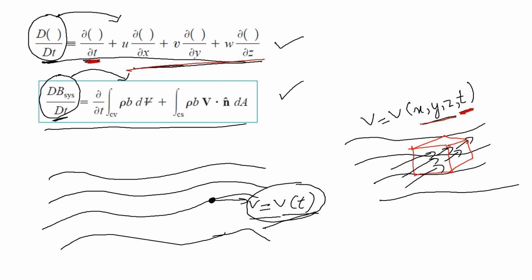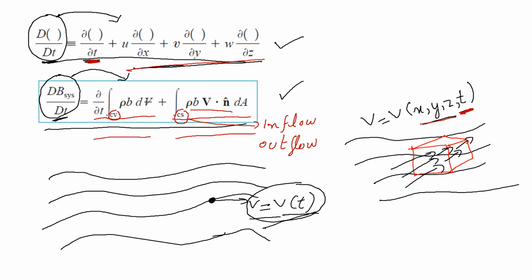Similarly, if we look at the Reynolds transport theorem, the first term on the right hand side gives us a partial change with respect to time of a certain extensive property inside the control volume, and is added with a change across the control surface. That control surface is our inflow and outflow surfaces. You remember this equation here, the dot product is representing the inflow and the outflow of the system, and this tells us about the position of fluid going into and out of the system.